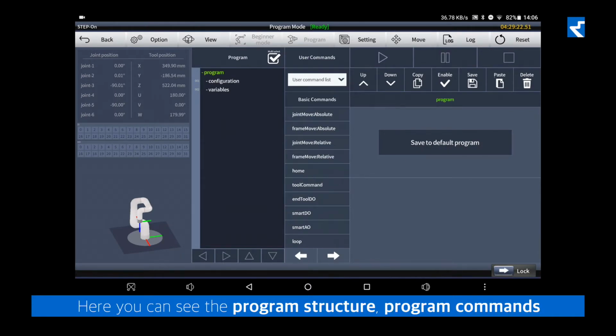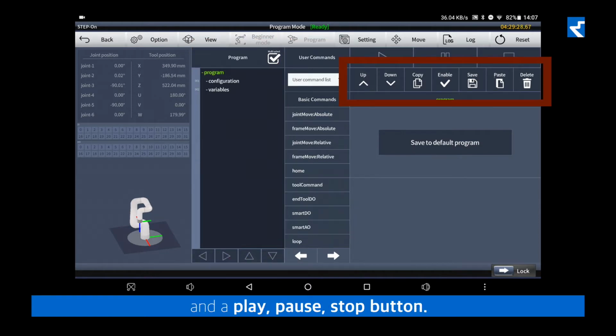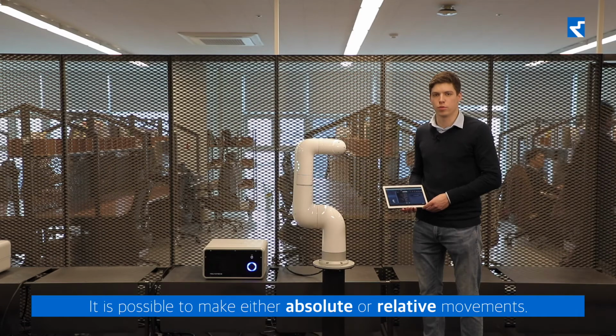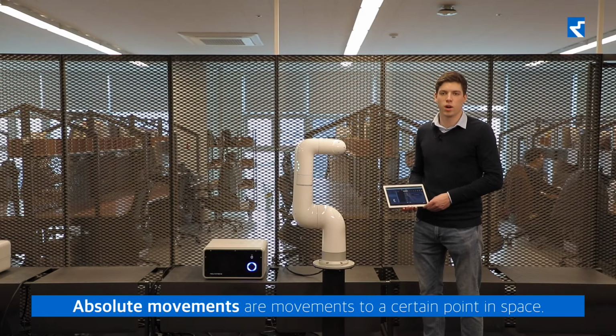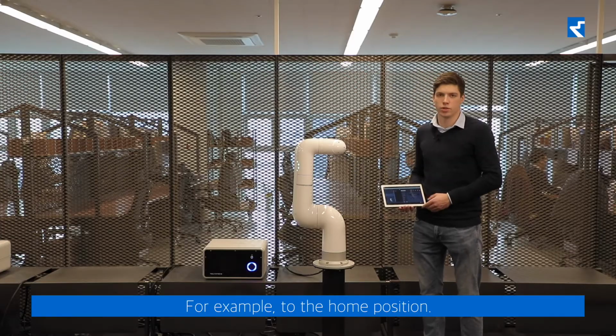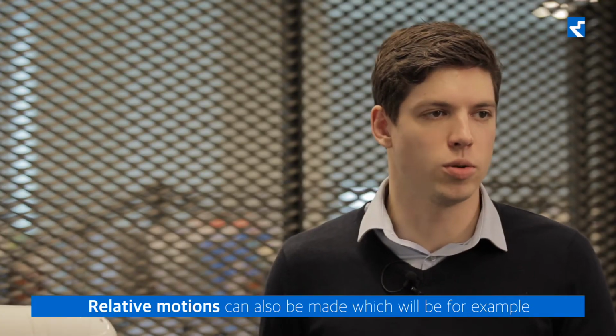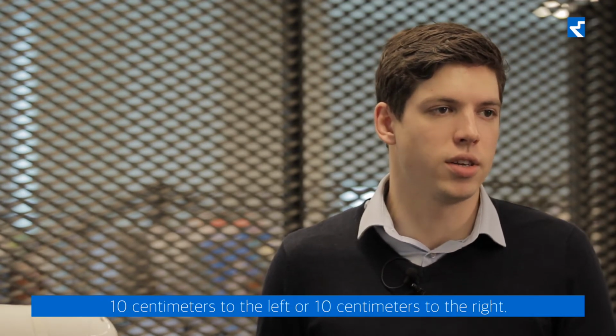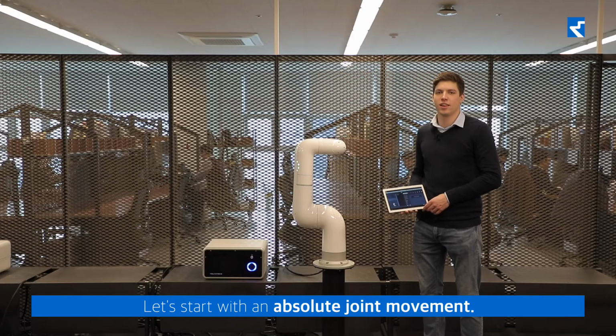program. Here you can see the program structure, the program commands, some command editing tools and the play, pause and start button. It's possible to make either absolute or relative movements. Absolute movements are movements to a certain point in space, for example to the home position. Relative motions can also be made, which would be, for example, 10 centimeters to the left or 10 centimeters to the right. Let's start with an absolute joint movement.